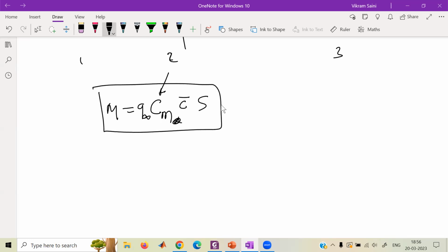Because you are flying at a certain speed, you have half rho v square, Q infinity, a certain positive dynamic pressure. C bar is a constant positive number, surface area is a positive number. The only number dictating whether the aircraft will pitch up or pitch down is Cm.